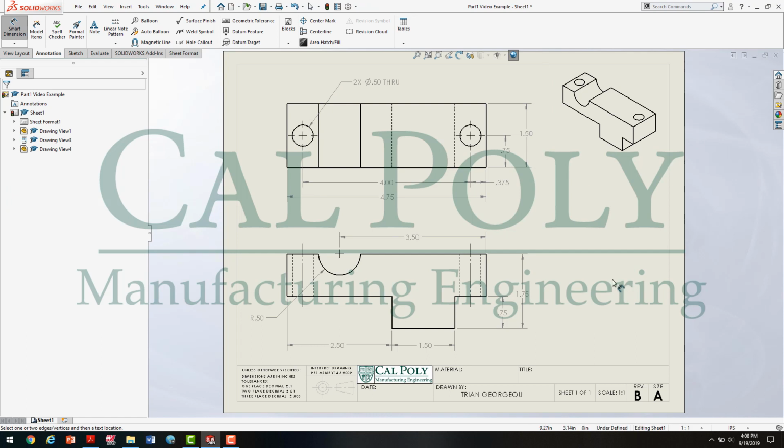At this point, we have a fully dimensioned engineering drawing. It fully defines the part. We'd be able to build this part in our lab if we really wanted to. Or draw it by hand, like we did in the orthographic projection practice. However, the one thing that's not finished on this drawing is the material, the title, and the date. So I place notes on my engineering drawing to specify the material, the title, and then the date.